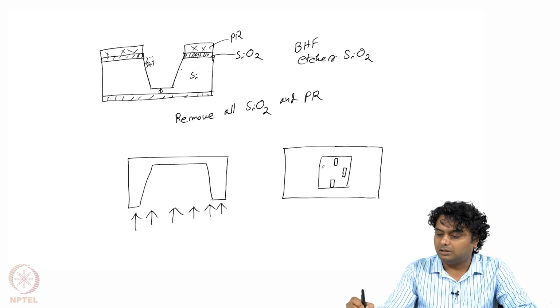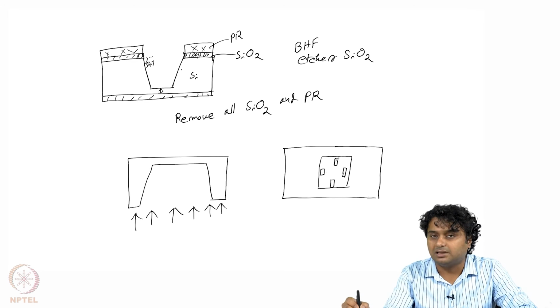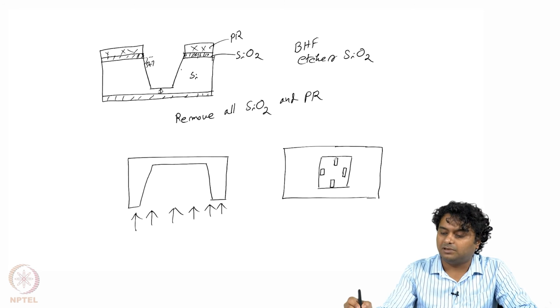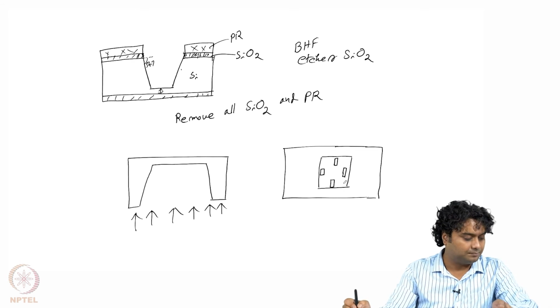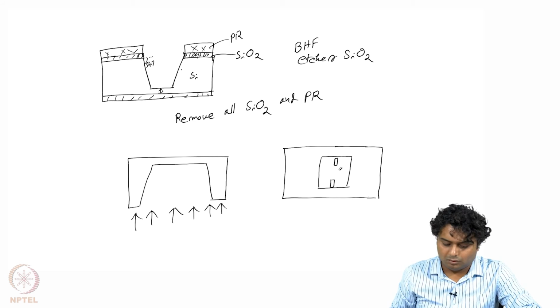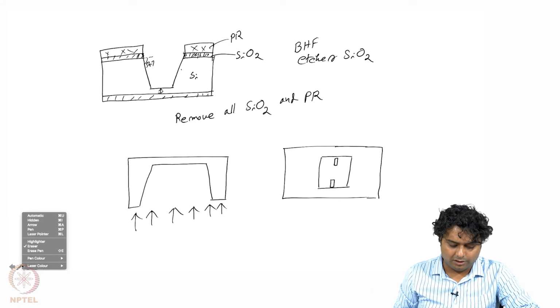And how do we put the piezoresistors? We will open a few spaces using lithography, and then we will dope boron into those spaces, right, and then these places of the silicon membrane will become piezoresistors. So we can align them like this, or we can put the piezoresistors according to our design requirement.